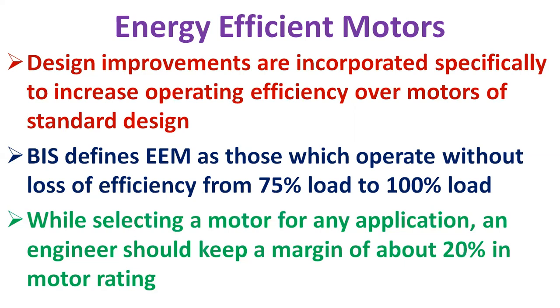While selecting a motor for any application, an engineer should keep a margin of about 20% in motor rating. Energy efficient motors automatically take care of the shortfall in efficiency. Many a times, economics have proved that even an existing running standard performance motor can be replaced with an energy efficient motor with a payback period of as low as 18 months.